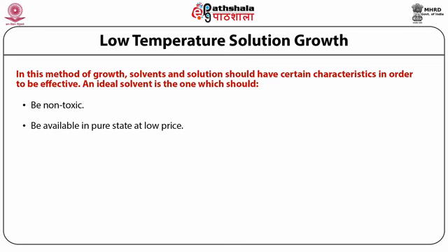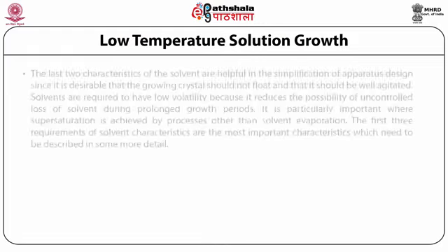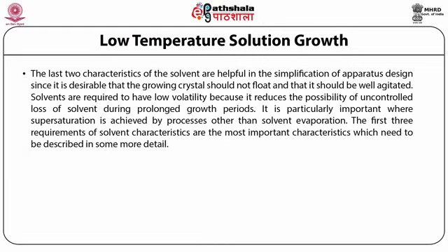be available in pure state at low price, be non-inflammable, have low viscosity, and have density less than that of the bulk solute. The last two characteristics of the solvent are helpful in the simplification of apparatus design, since it is desirable that the growing crystal should not float and that it should be well agitated.